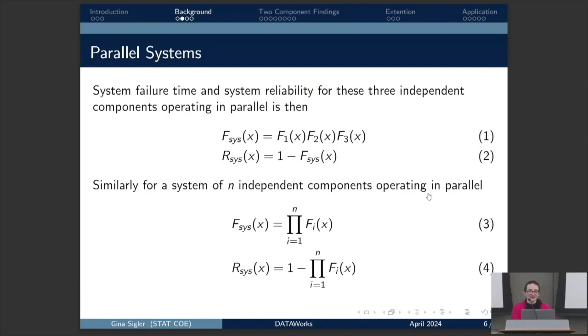So a little bit of math. I warned you. Going to be a lot of formulas up here. These are the simple formulas. This is talking about how you actually measure the reliability for systems in parallel. So if you're going to figure out system reliability, which is that R sys up there, it's 1 minus the chance that you're going to fail, right? So we have failures, and we have survival, and they're inverses of each other. So one minus the other, right? We can go back and forth. And if you've got a whole bunch of components operating in parallel, all I need to do is figure out what their individual failure rates are and multiply things together.